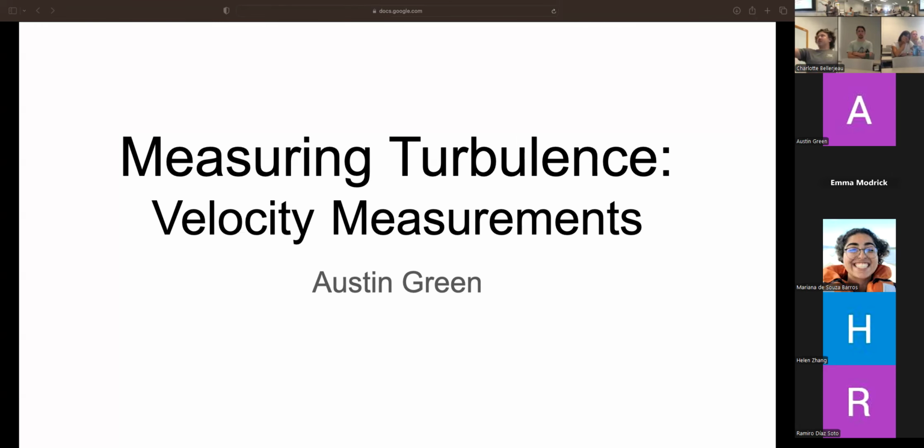So as was mentioned, we're going to be looking at how we measure turbulence or turbulent quantities or parameters using specifically acoustic instruments. So that's your ADCPs, your ADVs, your TTVs, your TPADs. I love those sorts of things. Later, Charlotte will go over our microstructure profilers, which are more like strain gauge kind of things. You can correct me if I'm wrong, but just a slightly different thing with different scales.